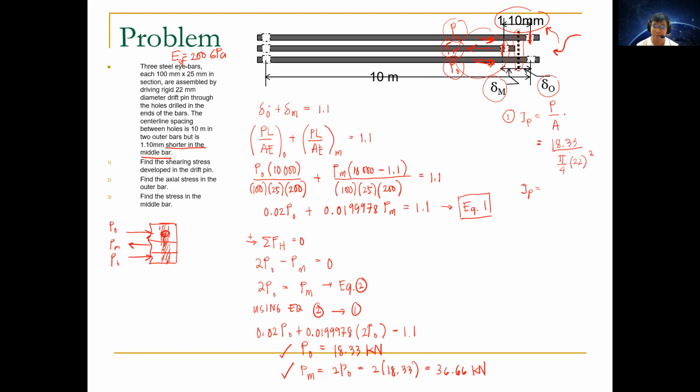If it's 0 point something, that would be in gigapascal because we are using kilonewtons. So keep in mind, kilonewton per mm squared gives an expected answer in gigapascal. But if it's a small number, try using megapascal, newton per mm squared, so the number becomes a bit bigger.